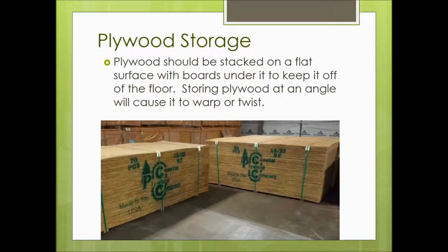Alright, now this slide deals with storing plywood, but this rule goes for any type of lumber storage. If you've ordered lumber and you're going to stack it up and you throw it all down in a big jumbled mess, then what's going to happen very quickly is that lumber is going to warp and twist, and you're not going to be able to use it.